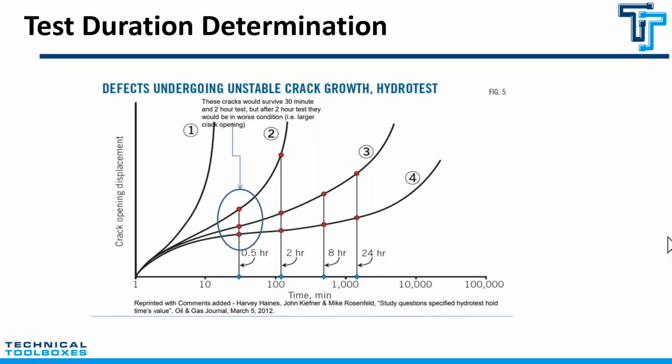Most pipeline operators do a 30-minute test, and others do around a 2-hour test. I'm actually giving a paper at NACE on this, and there's reason for some of this because of the type of failures and cracking you're seeing on your pipeline. Again, this is something we could work with you on and set up accordingly. That's strictly under review, and please contact us so we can work together to address your specific issues.